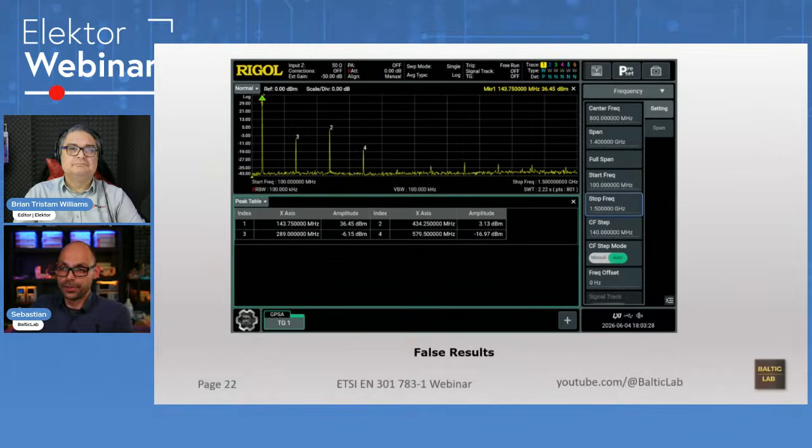Remember, the radio is tuned to 145 megahertz, the center of the 2-meter amateur radio band here in Germany. And the frequency is accurate. And the Rigol spectrum analyzer is not cheap. That RSA 6K is, I wish it would only be 6K, it's closer to 10K in money. And if you look at the frequency, the fundamental is given as 143.75 megahertz. So something went wrong here. And this is a very common mistake. It's an easy mistake, but I'm going to claim it's fairly unknown.